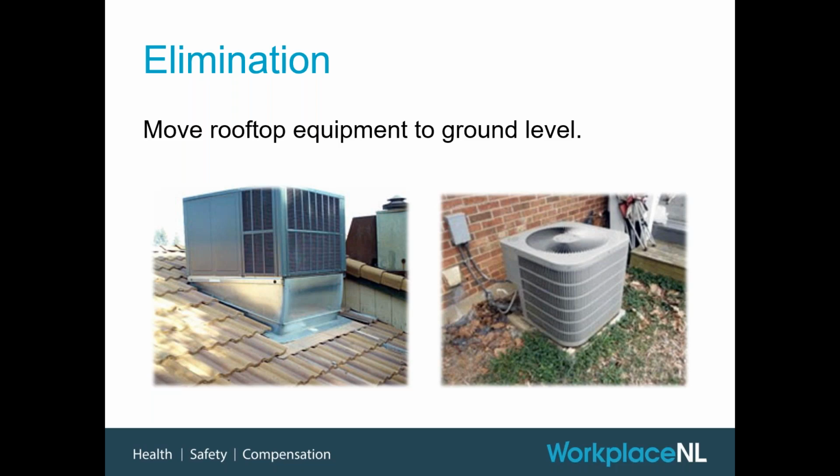But when we think about the amount of effort that has to go into maintaining these rooftop pieces of equipment, especially if they're within 6 feet of the edge of the roof, which is our rule of thumb with regards to the roofing industry, it requires a lot more administrative overhead, because then you're getting into situations where the person has the potential to fall off the roof, and perhaps you have to have a guardrail system, perhaps you're going to use personal fall arrest. But if we can just take that rooftop equipment and move it to ground level, we no longer have to get up on that roof, and that certainly might be of benefit in some situations.